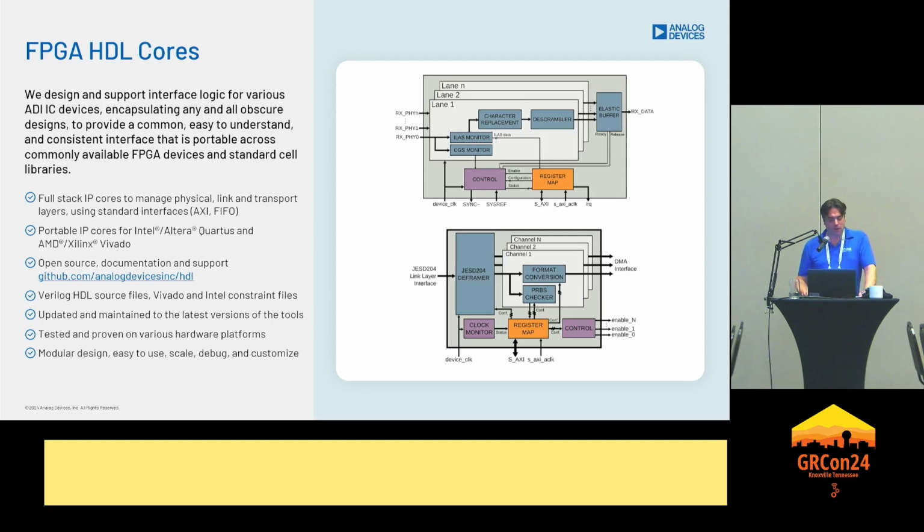I think a few bullets here. Again, it's all open source, it's documented. It's typically Verilog source files and Intel constraints files. We test them to the latest versions of the tools. So all these FPGA vendors, they have at least 2 releases a year. We try to follow those. They are tested and proven. They're modular, easy to use, scale, debug, and customize.